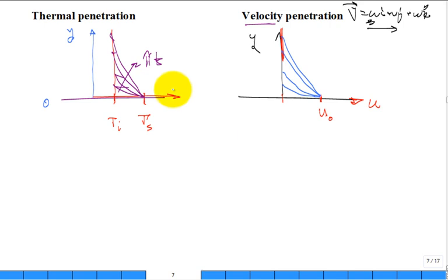All right, what is our governing differential equation for the penetration of temperature into the semi-infinite solid? It was the equation we just wrote. It was the second derivative of temperature with respect to space. If you want to put a k over there, that's great. Then you have rho c partial of T with respect to time. We brought that k underneath the rho c, and we said, hey, that's alpha. K over rho c is alpha, so a little shortcut, there it is: 1 over alpha. That's our governing differential equation.